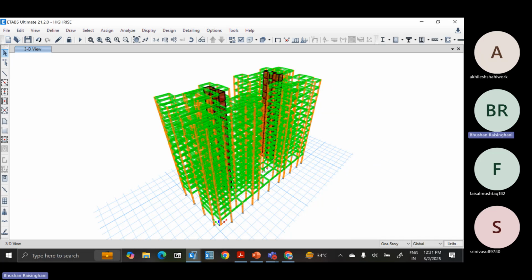So this is how it works in the analysis and design of high-rise buildings. So one building with podium, second building with podium, whatever is the worst case in design, you take it for the podium. For each building above the podium, you will do independent design, and combined analysis for both the buildings for the podium also you will carry out if there is a backstay effect. Okay, so substructure and superstructure analysis, both you will conduct, combined and separate.